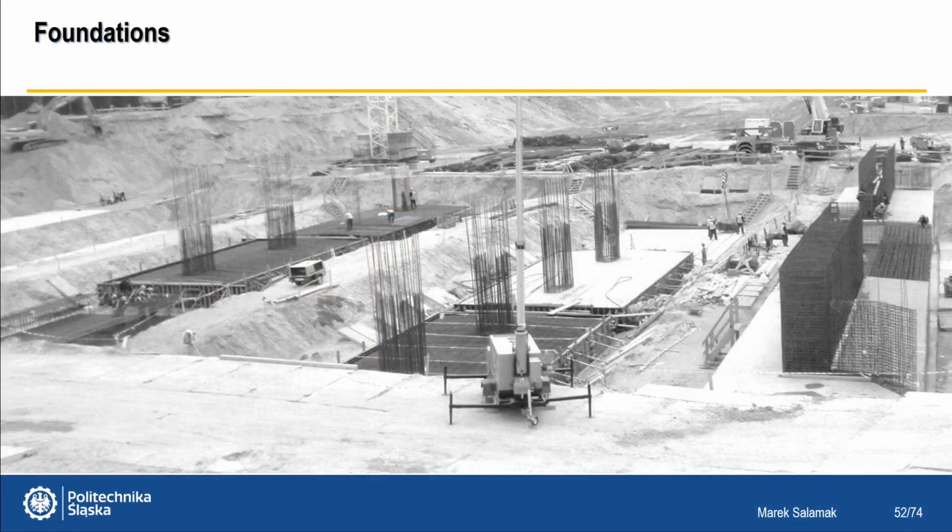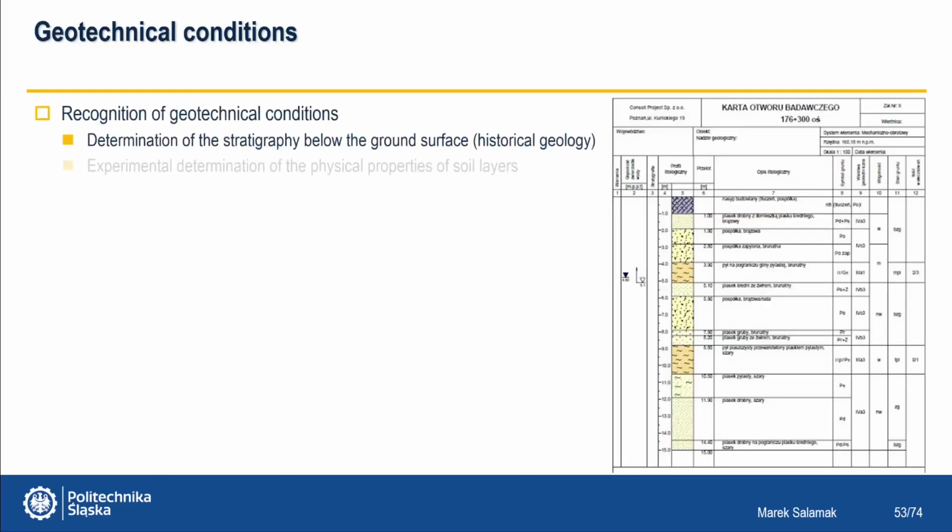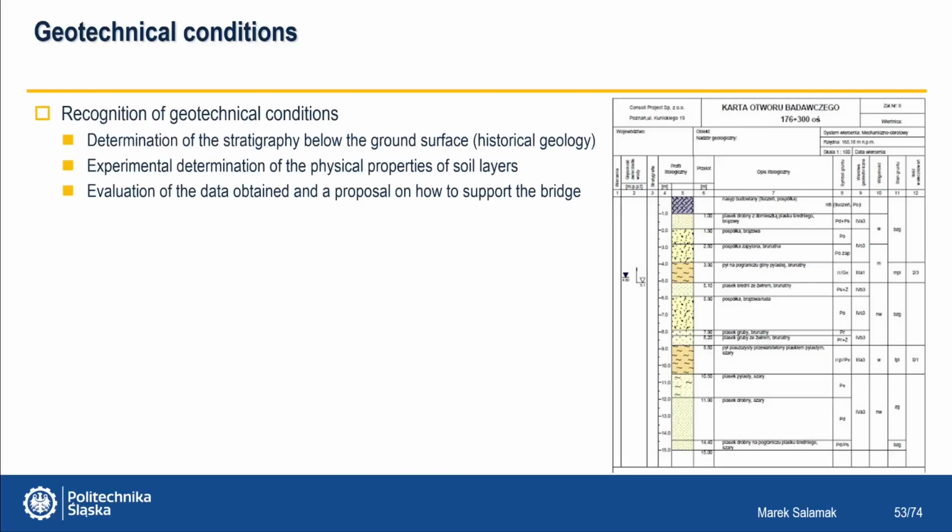Finally, I'd like to discuss the issue of bridge supports foundations. Before starting the design of the foundations, the geotechnical conditions of the substrate should be recognized. The stratigraphy under the ground surface is determined with experimental determination of the properties of the soil layers. The evaluation of the obtained data during geotechnical tests serves to provide a proposal for the foundation of the bridge.